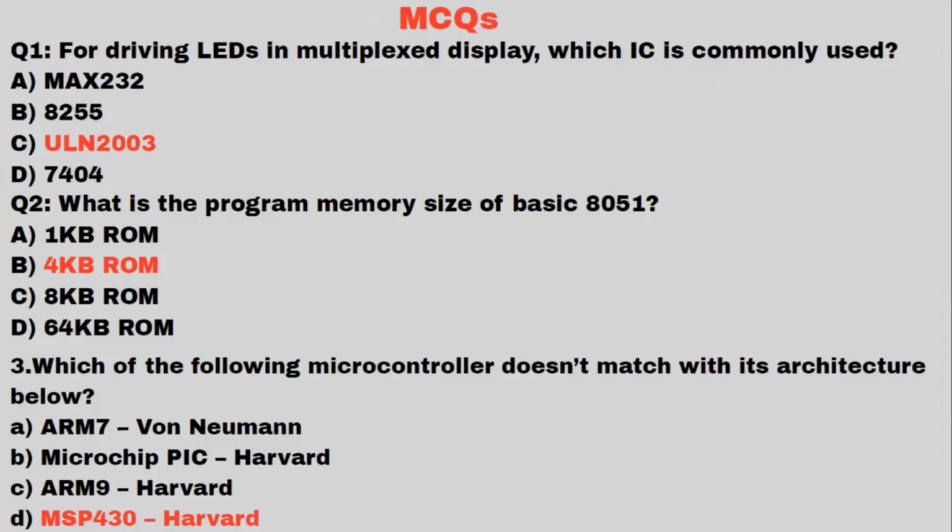Question number 1, for driving LEDs in a multiplex display, which is the commonly used IC? ULN2003. We already studied this in the first part. ULN2003 is the IC number which will drive your LED. Question number 2, what is the program memory size of a basic 8051? It is 4 kilobyte ROM. Question number 3, which of the following microcontrollers doesn't match with the architecture below? Please remember, it is not asking about matching, it is asking doesn't match. So MSP430 as Harvard is wrong. It doesn't match. This was question number 3.